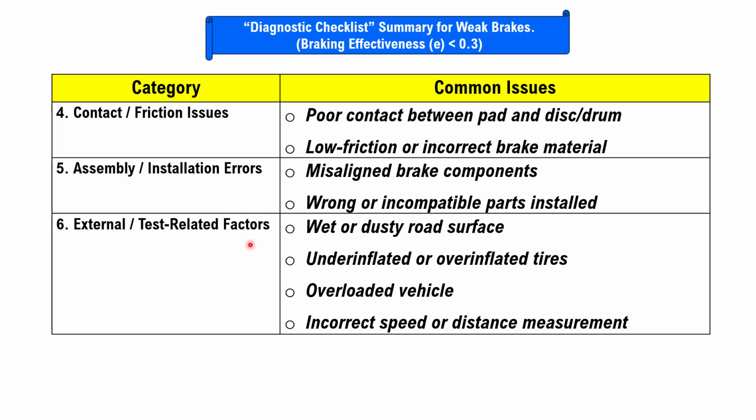The external factors which could be resulting in lower braking effectiveness are wet or dusty surface, underinflated or overinflated tires, overloaded vehicles, or incorrect speed or distance measurement.